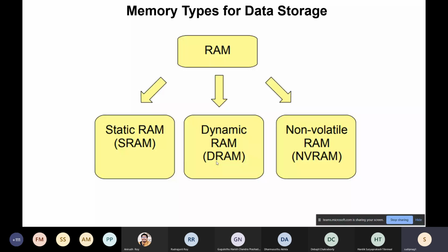If you take any VLSI technology, 180 nanometer or 65 nanometer or even 22 or 7 nanometer these days, just think about accommodating 6 transistors and their connections in between versus accommodating one transistor and its necessary connections. The space is significantly reduced.